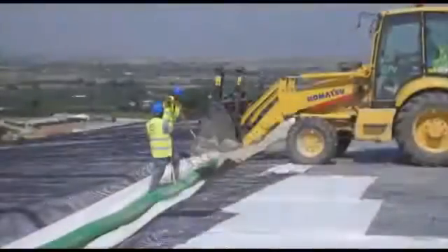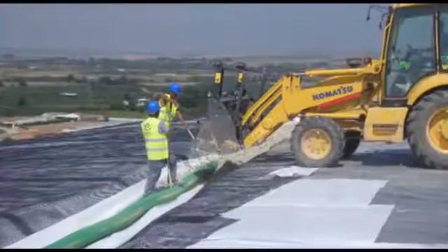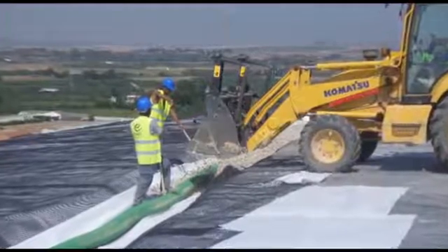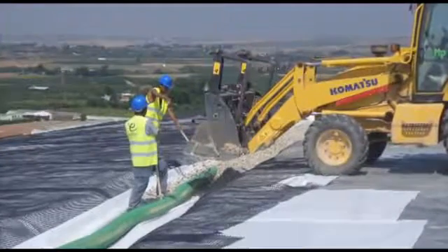Landfills also utilize geosynthetics to perform a drainage function, as controlling the movement of leachate and water within and around a landfill is a key design issue. In landfills, the geosynthetic drainage layers are wide rolls and will help move the leachate to collection points that will assist the engineer in removing the leachate from the structure without contaminating the surrounding groundwater.